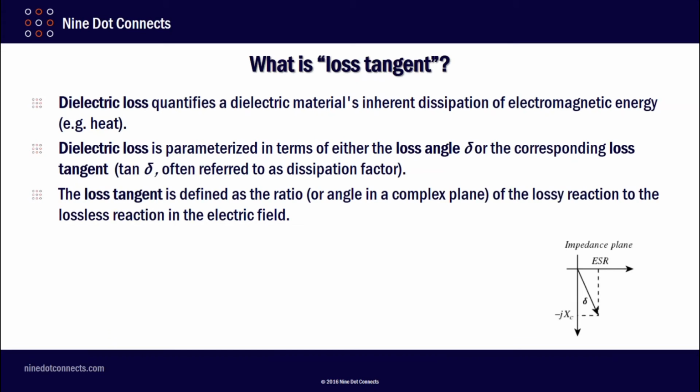That loss tangent is defined as the ratio or angle in the complex plane of the lossy reaction to the lossless reaction. If you'll notice down here in the lower right hand corner, we have a picture of a capacitor dealing with ESR, and then we have the reactance of that capacitor. Notice that their delta, the angle they're measuring, is between the imaginary axis and the real. It's not on the right side that you typically would think about.